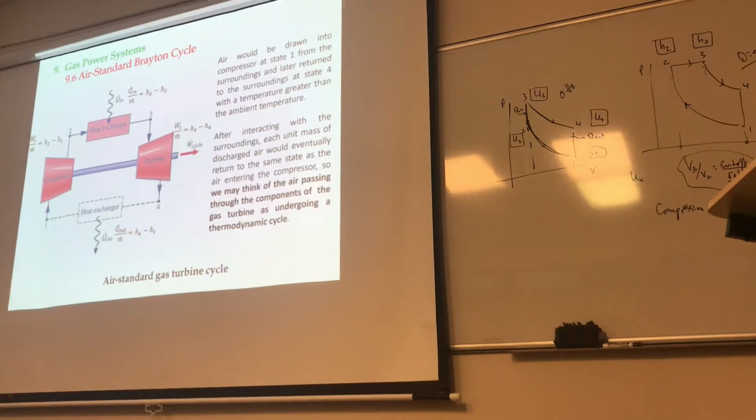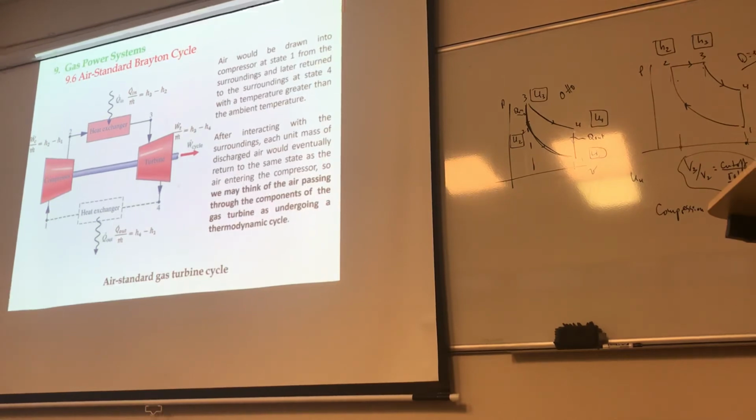It's a constant pressure process, just like the vapor power cycle. What is the assumption that we were making there? It's a tube that carries fluid, right? What we are assuming is that there is no friction between the fluid and the walls of the tube, okay? That means we are not losing pressure, and therefore it is a constant pressure process, okay?